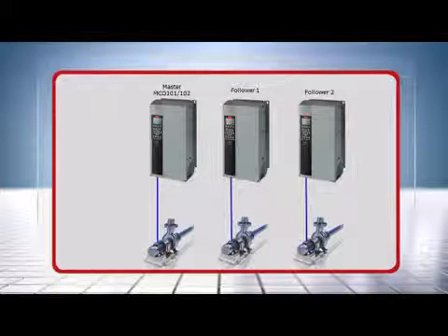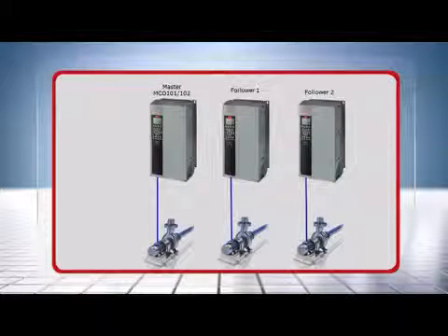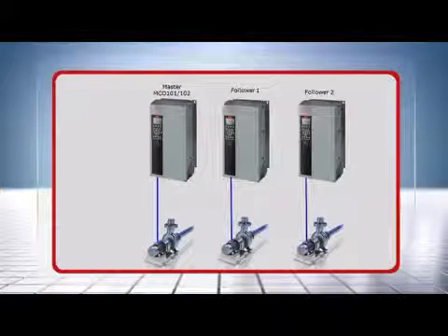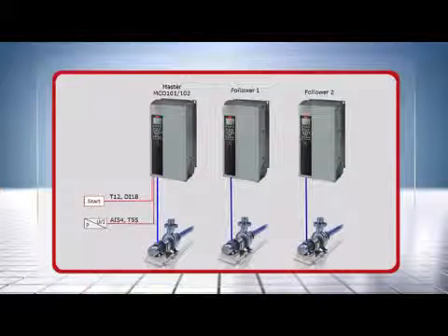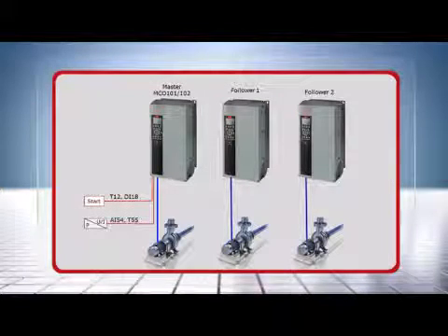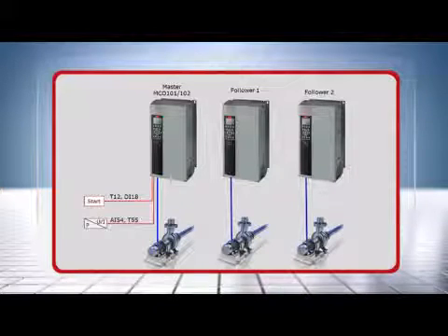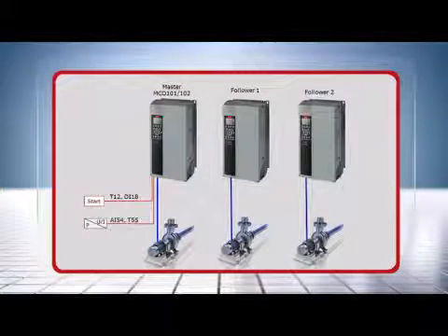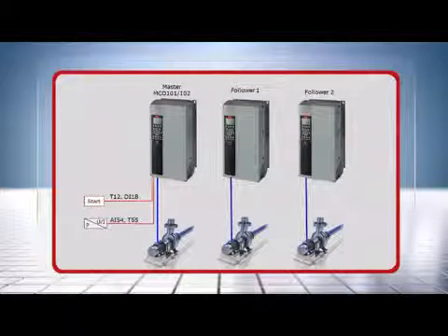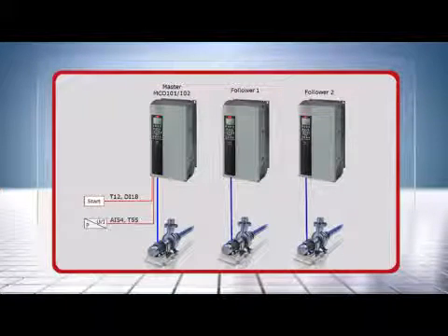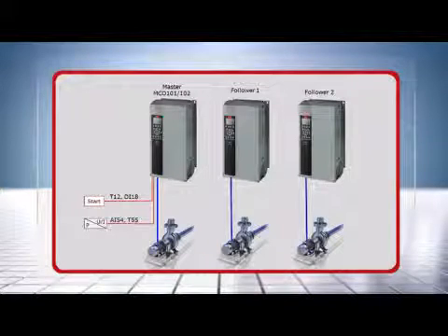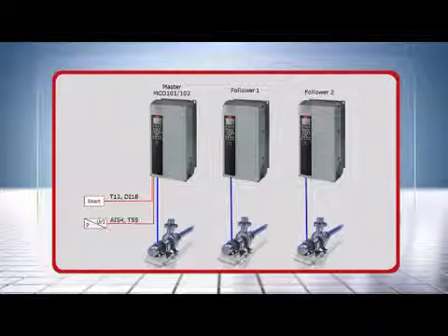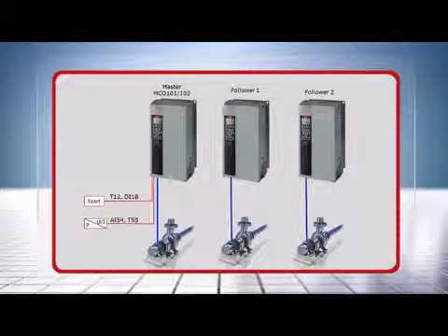In a master follower configuration, each pump is speed controlled and connected to a drive. The start signal for the Cascade application is an external signal connected to digital input 18 of the master drive. The master drive runs in a closed loop process and therefore requires a feedback signal. This feedback signal is provided by a pressure transmitter connected to analog input 54.